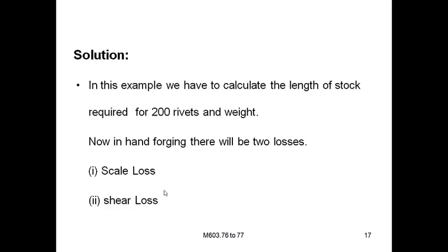Scale losses and shear losses you can neglect. Draw forged means it is a hand forging. If it is a hand forging, and the problem specifies it is draw forged and hand forged, you have to consider only scale loss and shear loss. The remaining losses you can neglect.